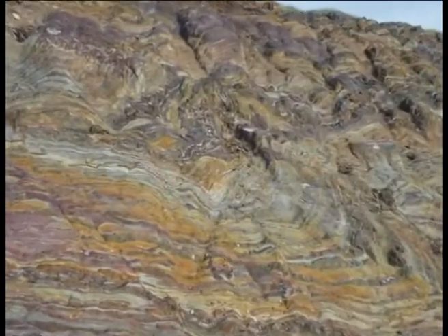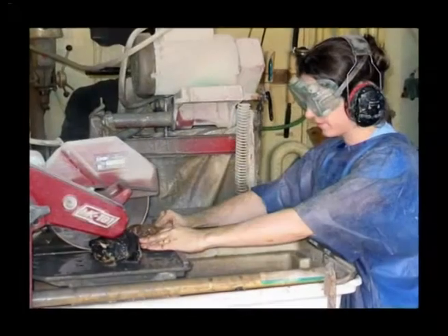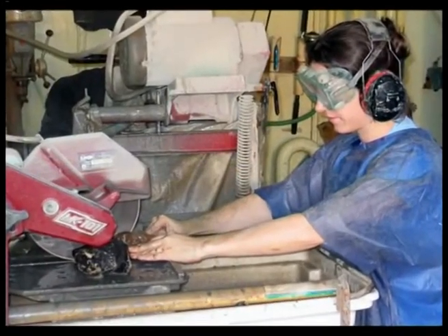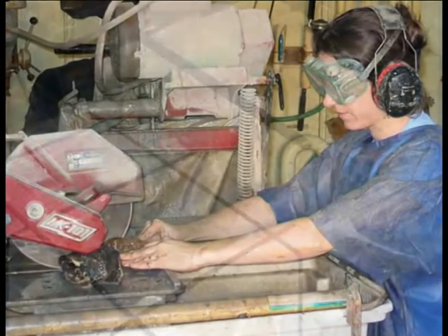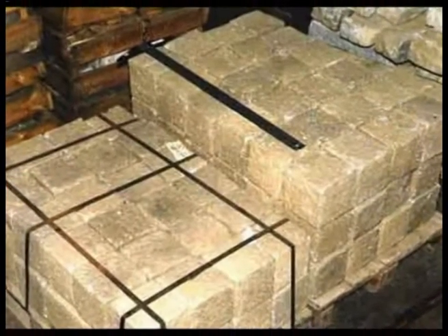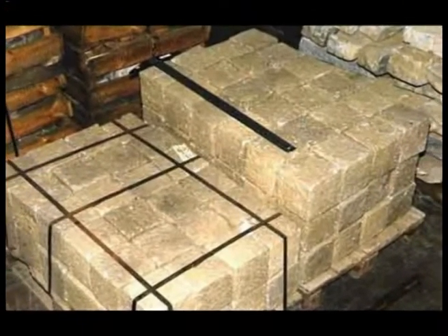Intact rock properties are determined from laboratory tests on small samples typically obtained from coring, outcrops or exposures along existing cuts. Common engineering properties typically obtained from laboratory tests include specific gravity, point load strength, compressive strength, tensile strength, shear strength, modulus and durability.